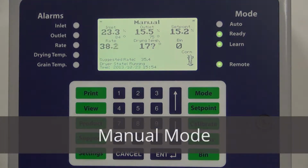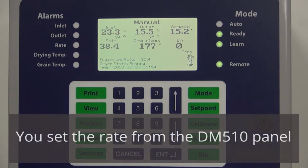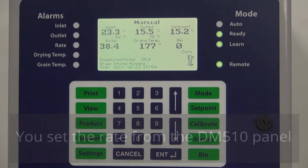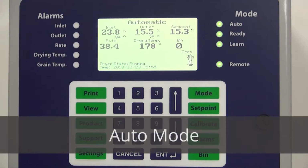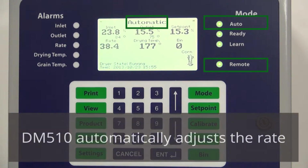In manual mode, you still decide on and set the discharge rate by yourself, but now you do it directly from the DM panel, without having to use the dryer panel. When you switch to manual mode, you will see that the remote light goes on. When the remote light goes on, the dryer discharge rate is being set from the Dryer Master panel and not from the dryer panel. Finally, in automatic mode, you tell the Dryer Master panel your moisture target or set point, and then you let it automatically make discharge rate changes for you.